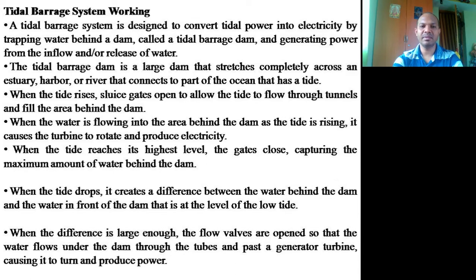The location of the barrage is important because the energy available is related to the size of the trapped basin. If the water you trap doesn't possess high potential energy, then the point of storing this water will not be useful.